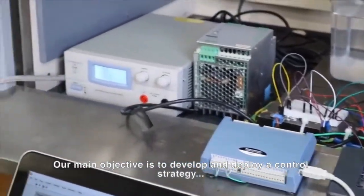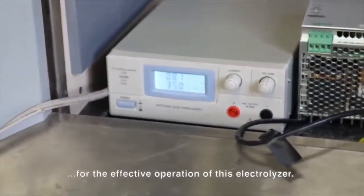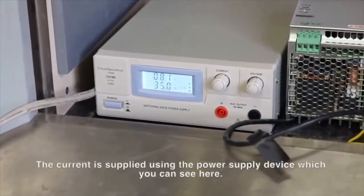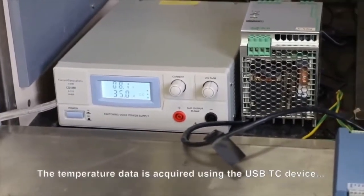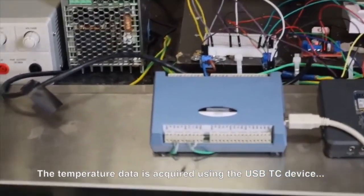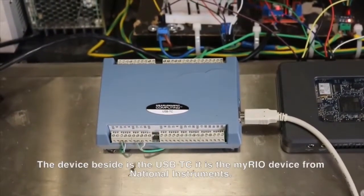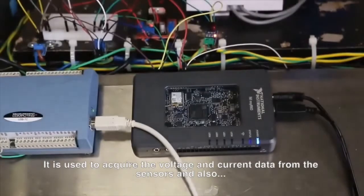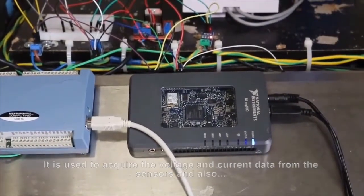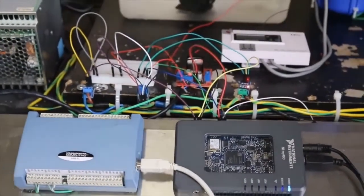So our main objective is to develop and deploy a control strategy for the effective operation of this electrolyzer. The current is supplied using the power supply device, which you can see here. And the temperature data is acquired using a USB-TC device, which is a data acquisition device from Measurement Computing. The device beside the USB-TC is the myRIO device from National Instruments. It is used to acquire the voltage and current data from the sensors and also used to implement the control actions or the control strategy.